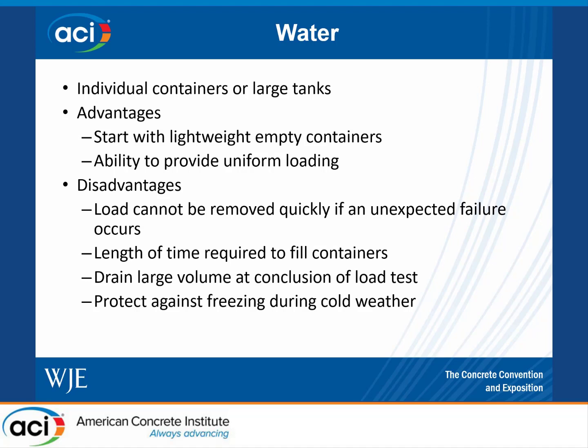Some of the key disadvantages, though, are once the water's in place, it's difficult to move it quickly if you have an unexpected failure, which is different than the hydraulic loading techniques. And it could also take a long time to fill all of the containers. You really need to check your water supply and your water pressure in advance so you have a good idea how long it's going to take you to get a large volume of water in.